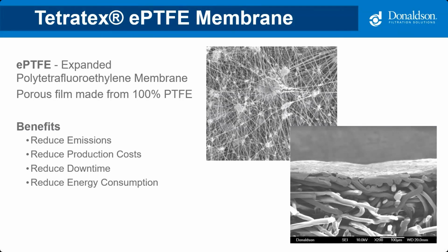And so the same type of concept that's maybe on a lot of your hunting coats and boots, where the water sheds off of it and no dust is able to get on it, that's used in filtration media as well. And the benefits of the EPTFE membranes: all the dust is going to slide off of it, especially if you have any moisture in your ductwork, and it's going to be extremely efficient, and it's going to last a lot longer because the dust isn't being allowed to penetrate into the media.